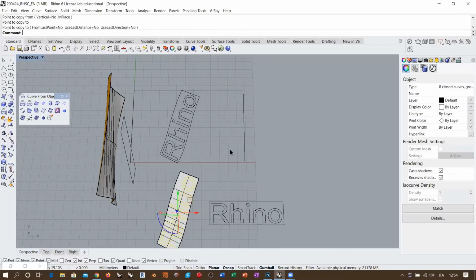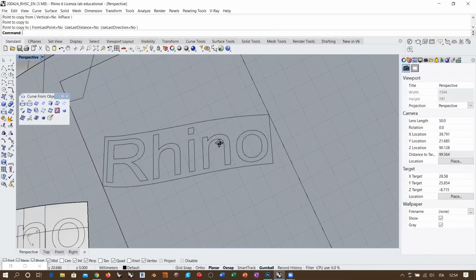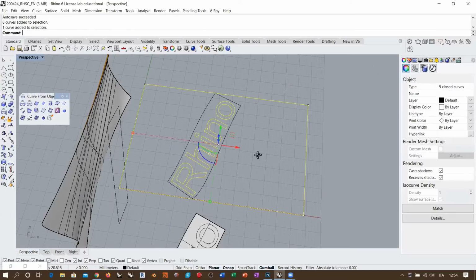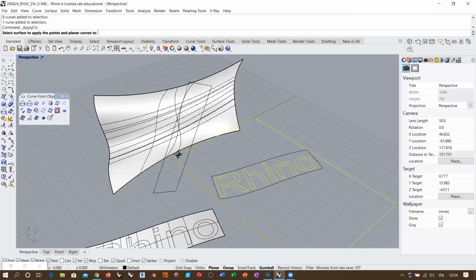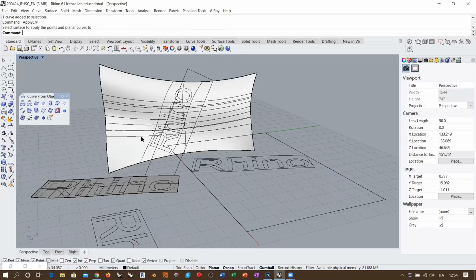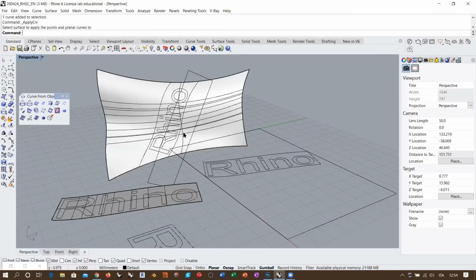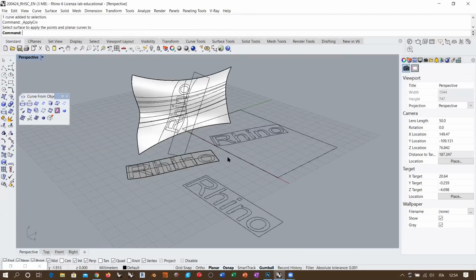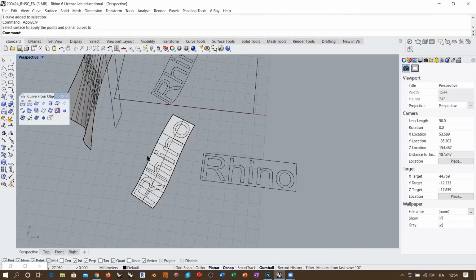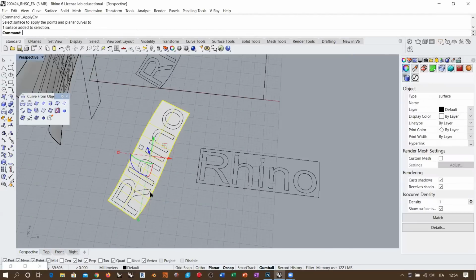And you see that I already got the first representation of this text. And once I'm here, I take this one and apply the UV curves onto this surface. So my writing is actually adapting to this surface here. Now you see that some weird things are happening in this process because in this case it's less evident because this sweep to rail is a little more regular, okay?